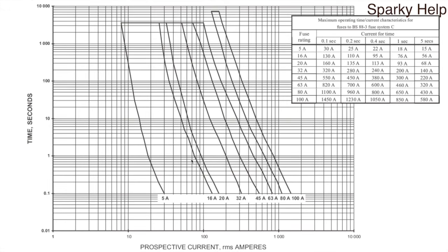So how do we use this then? Well, it's quite good at finding disconnection times for the amount of fault current, or vice versa. If you know the fault current or the time, you can work either direction. So my question would be, how many seconds are there in an hour? Well, we're all thinking it's 3,600, because that's what it is. So up here there's 1,000, 2,000, 3,000.